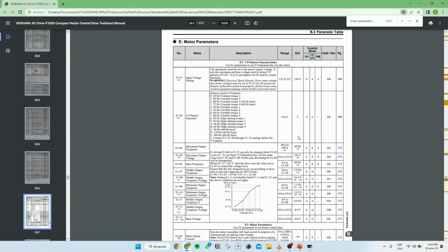Now, how do I know that it's this? Because it's telling me motor data or motor setup. So we also need to be smart in English. And generally, you also need to look for kilowatts or power, and look for amps or current, which is the data that is going to help us to enter this data plate.